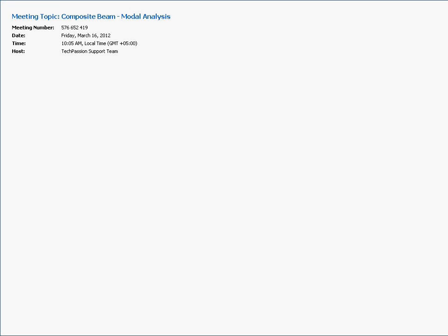Especially for people who could be on either side of the story. You could be somebody who is into testing alone, or you could be somebody who is doing finite element analysis alone. So there is always a question about, okay, how do I know if my results are right? So especially if you're doing simulation, it's important to take the test data with the prototype and do correlation. There are several metrics to capture correlation. One of them is MAC, Modal Assurance Criteria. There are other metrics also.